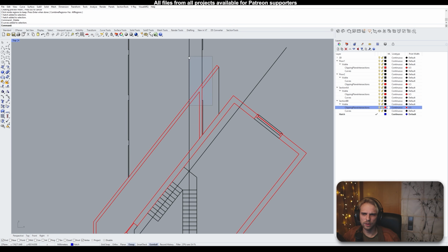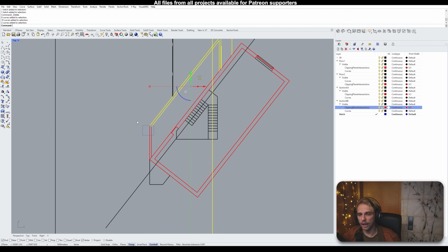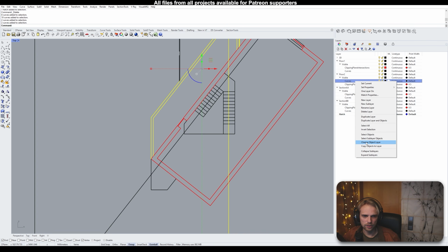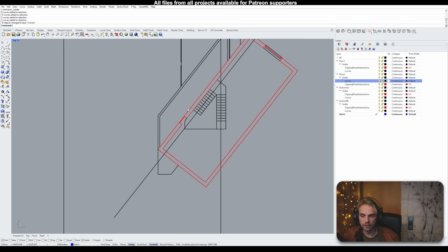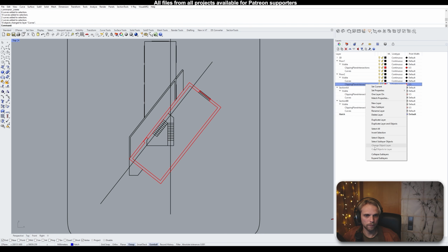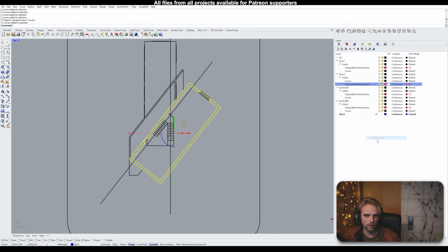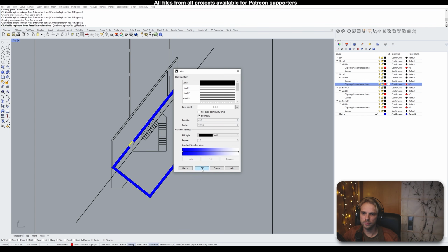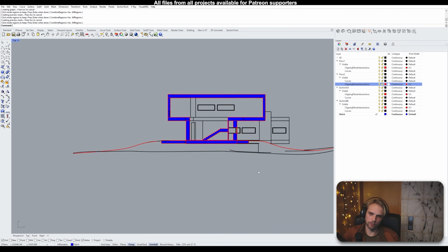So what I want to do with the railing, I'll lie about it and say that it's actually in floor 2. It belongs to the curves layer, not the clipping plane intersection, so that we are actually not cutting through it. We're only cutting through the outer envelope. And I'll hatch this one, just like that. Okay, sorry for the wait.